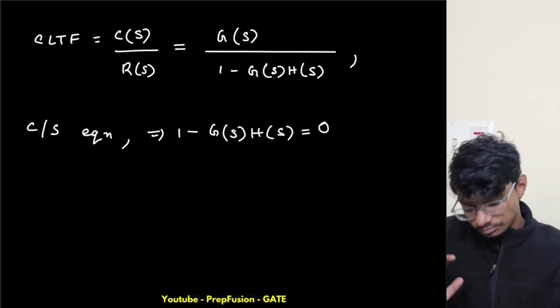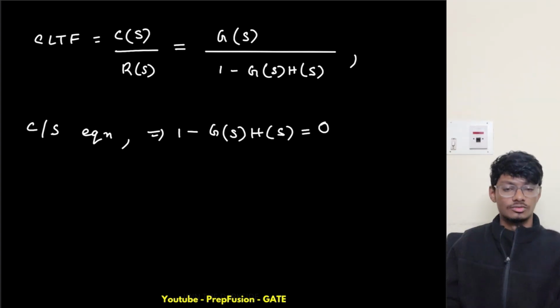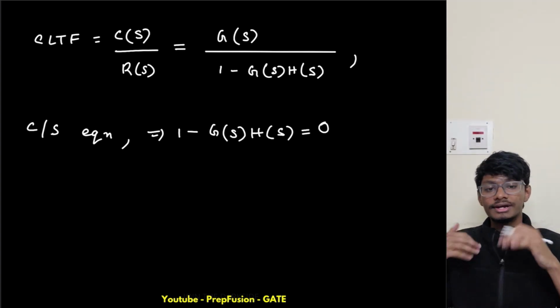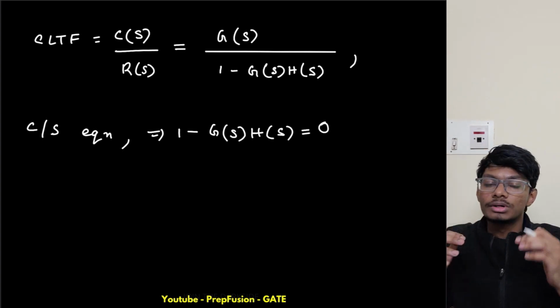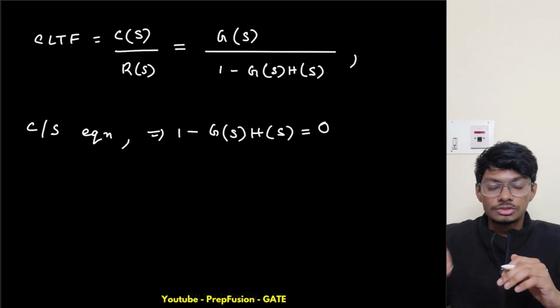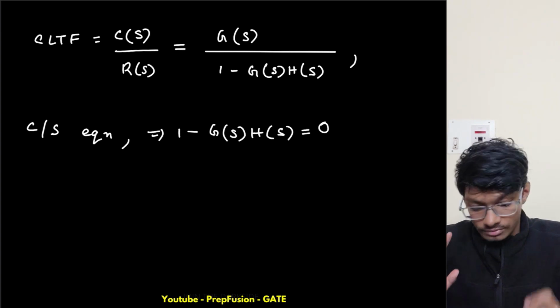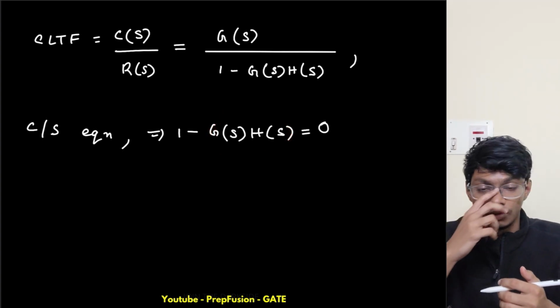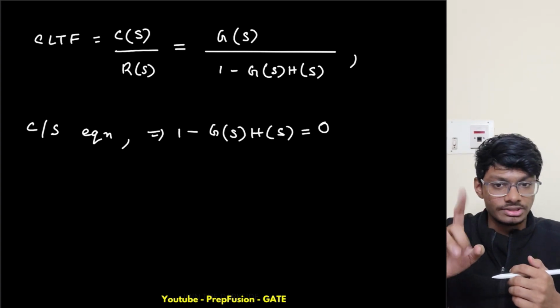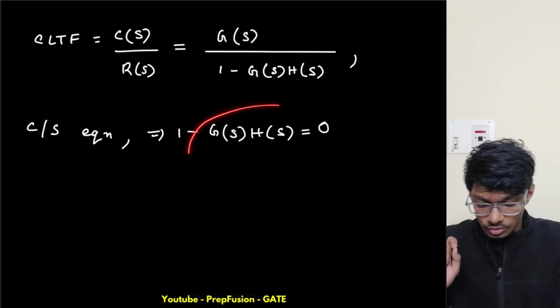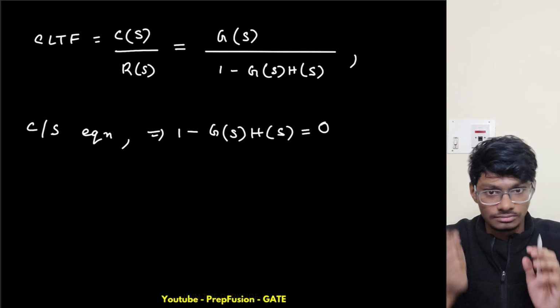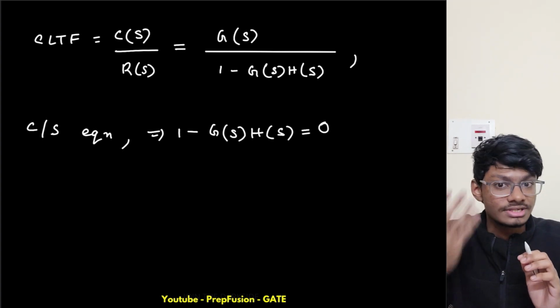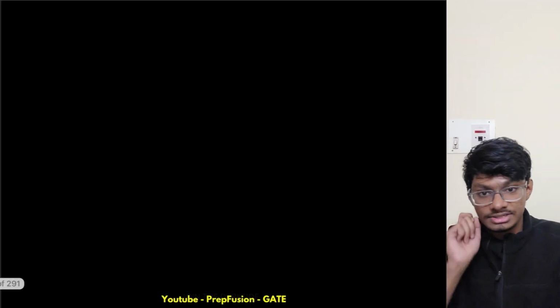So what does change due to this? Remember what condition just changed? When we studied the normal root locus, initially, what did we first derive about this OLTF? We derived two things, right? I hope you remember. One was the magnitude condition, another was the angle condition. Can you tell me what changes here? Just think, what condition changes here?